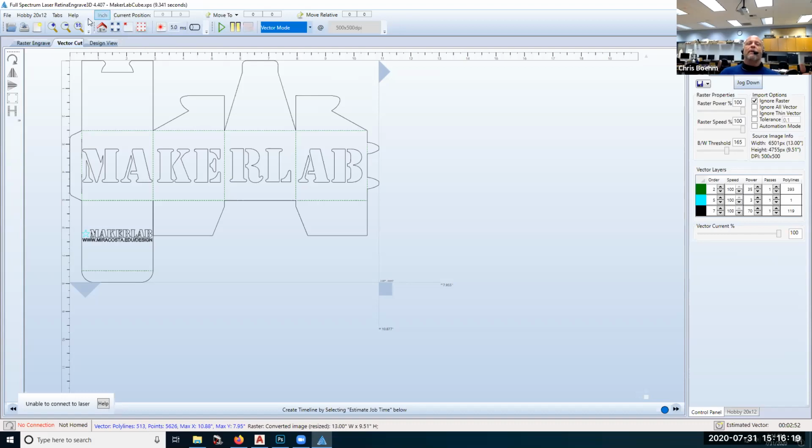Once we have walked through preparing the actual cutter, we would hit start job, and the laser would start to move along our lines, and we could actually watch that red line as it tracks. We could pause the job, and that would stop it right where it is once you hit pause. Or if you actually hit stop, it would go back to the origin point. So that's for a couple of things. Let's say you decided, uh-oh, it's too much power, or it's not enough power. Let's send it back and change the power over here. This gives us the option to do that.